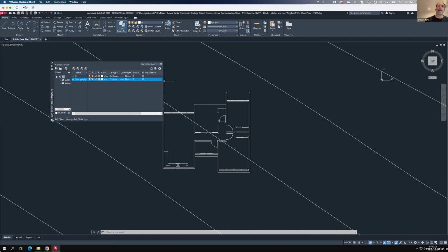Computers weren't very powerful. And as you started to work on really large drawings in AutoCAD, you needed to decide when you turned off a layer whether you wanted to keep the lines in the memory of the computer or whether you really wanted to turn them off. And so the on-off keeps the lines in the memory of the computer, keeps them in the RAM, so they're easier to turn back on. And the freeze and thaw removes them completely for the time being. So there's a subtle difference. In today's world, they are exactly the same. They don't do anything. Our computers are strong enough and powerful enough never to have this become an issue, but it's stuck around as an AutoCAD thing.